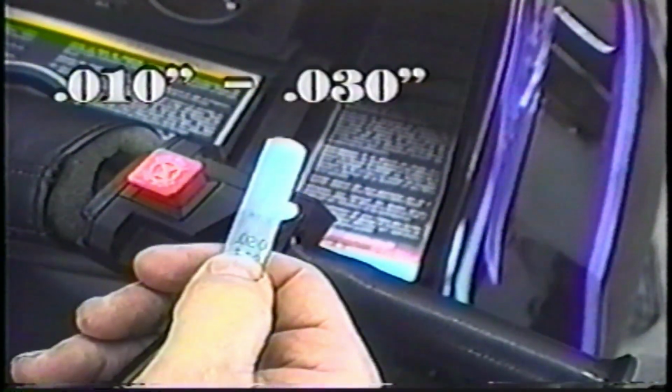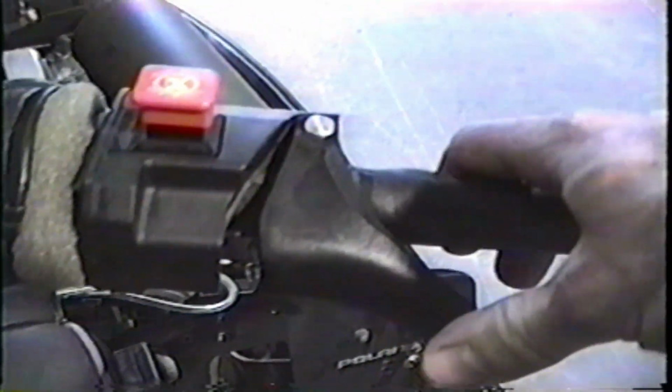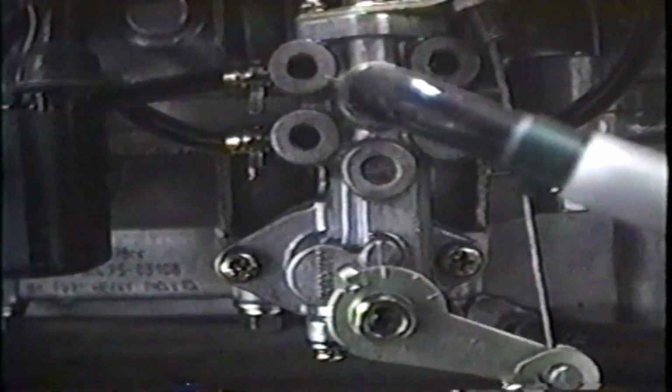The snowmobile throttle cables should be adjusted so that there's 10 to 30 thousandths of an inch clearance between the throttle lever and the throttle housing. Easy throttle models should have at least 50 to 60 thousandths of an inch clearance. If this clearance is excessive, the throttle flipper switch contacts will close the circuit before the pivot pin switch opens, causing a bog or a backfire. If adjustments are made to the throttle cable, don't forget to check the oil pump adjustment.